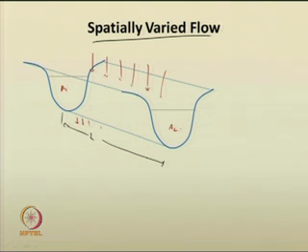So, why do we have to deal with spatially varied flow separately compared to gradually varied flow? Due to the addition or reduction of water, there will be much change in the energy, or the energy and momentum are getting changed. So, you have to use those correction factors. Not only that, you have to employ certain principles, because as the discharge is not uniform, you cannot directly use whatever principles are used for gradually varied flow in such cases.